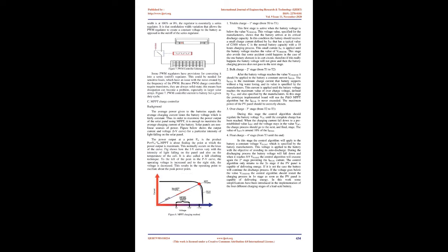In this method, the charge current is approximately 1/8 of its ampere rating. The excess voltage of the supply circuit is absorbed in the series resistance. The groups of batteries to be charged should be connected so that the series resistance consumes as little energy as possible. The current carrying capacity of the series resistance should be greater than or equal to the required charging current, otherwise, the resistance will overheat and burn out.